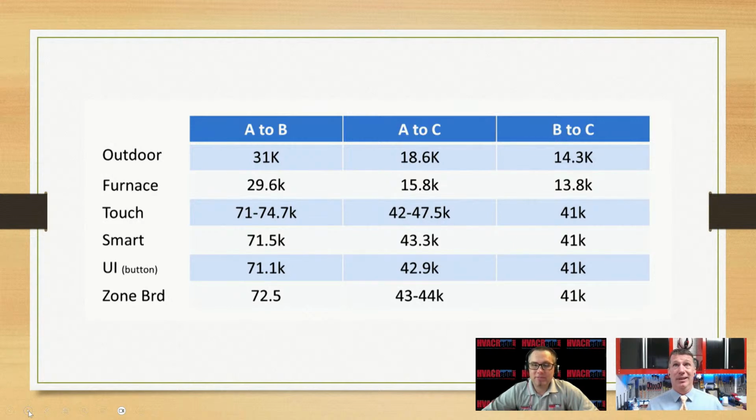So they reference ohms in thousands. If it's anything outside those parameters, I imagine they give you a plus or minus 10%, like most manufacturers. If it's in or out, that can tell you if the power supply of your board is bad, just like we do with PSC motors, compressors, you name it. I'm starting to see some similarities in here. If we know how to use a meter, we can work on these really scary inverter, modulating, communicating things that are out there. There is more service data for these systems than for anything else that we work on.